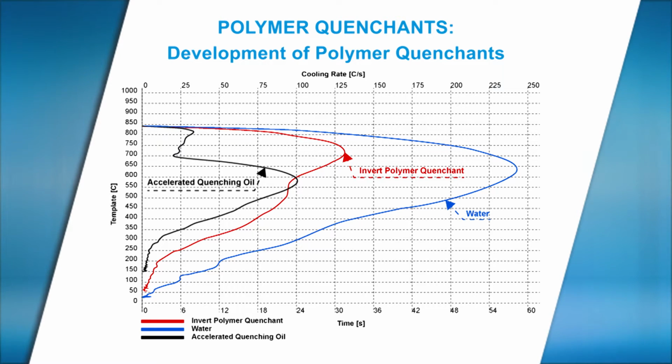Heat treatment operation can be carried out with these water-based quenchants, which would either be impossible or extremely difficult with oil. This particularly relates to spray quenching in induction and flame hardening processes, where a high degree of fire risk exists when using oil.